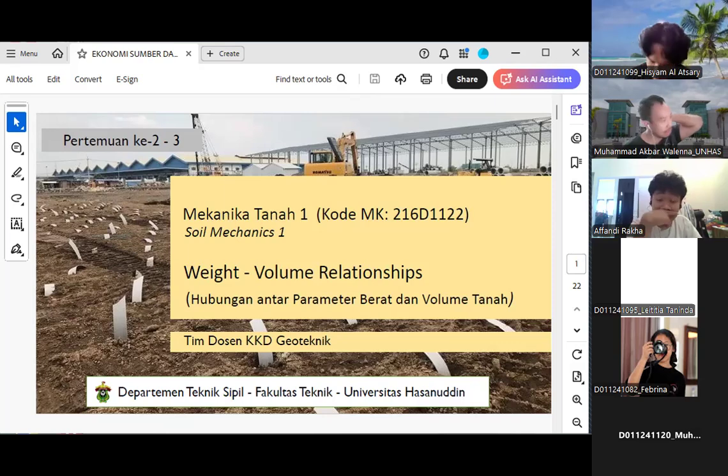So it is important, right? Because we don't want to construct something on soil that will compress drastically when we put some infrastructure above it. Okay. We would like to also know how soil behaves in relation to water. We would like to know whether the soil holds water, whether the soil will behave in a way that it's going to expand when it absorbs water. We would like to also know how dense the soil is. So these considerations are very important when we are designing a foundation.